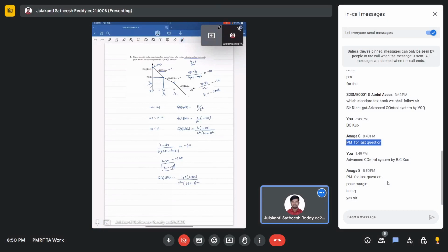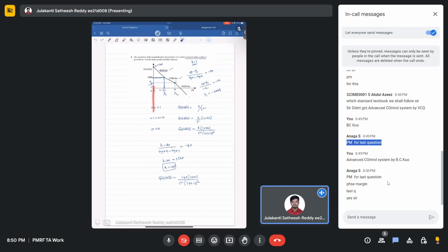Okay, so now we know this transfer function, right? Now we are able to get it. From this, what you need to do is make the phase plot also. It will be minus 180 up to this point. Then again, because of minus 20 slope, it is going to be minus 90, so again it is moving towards minus 270. This is minus 270.